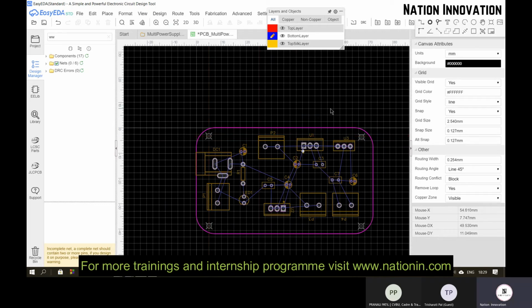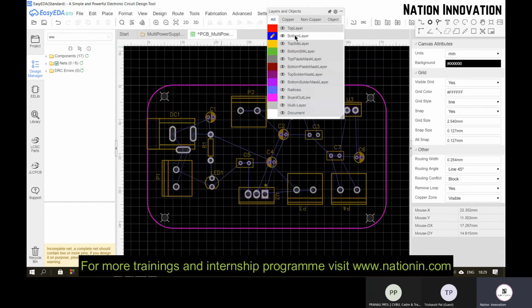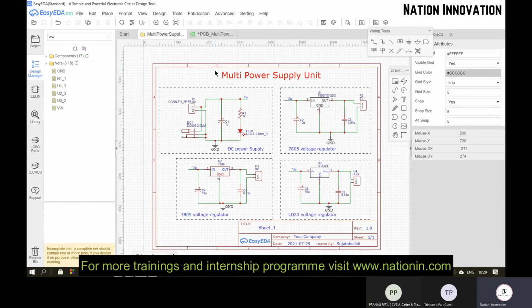Now we will go with the routing. For that, select the bottom layer and press W key. If you want to change its width, I suggest you go for 1 mm track width for this DC power supply, because the voltage supplied by this switch will be very high. So go for the 1 mm track width here.